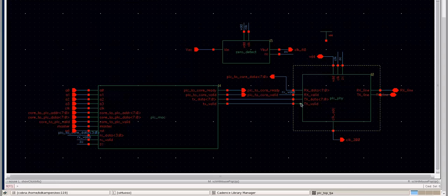In order to simplify access to the shared communication medium, the communication is arranged as a master-slave configuration, in which the master module is responsible for initiating communications and requesting data from the slaves spread throughout the house, while the slaves are only responsible for monitoring the power line and responding to the request for data. So this state machine is simply a controller that allows this master-slave type configuration.